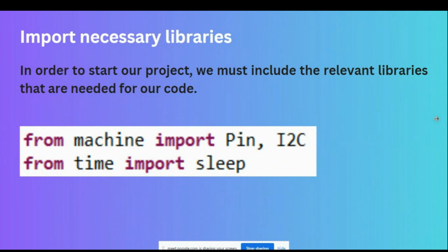Right. So in our activity, we need to make the code using the MicroPython language in order to activate the push buttons and to handle the LEDs. As we did in previous sessions, first we need to import the libraries. Here we are just using two common libraries, the machine library and the time library.